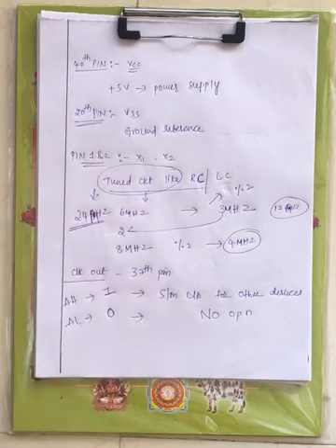At the 40th pin we are providing VCC, through which you can provide a +5 volt power supply to the microprocessor in order to operate it. At the 20th pin is VSS, which is used for ground reference. At pin number 1 and 2 we have X1 and X2.